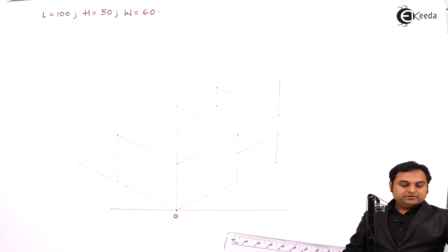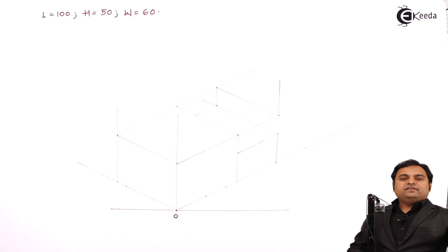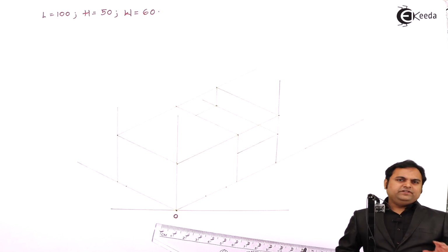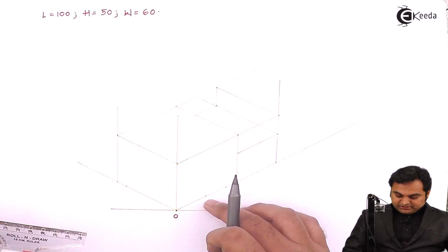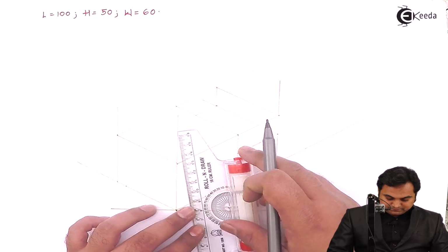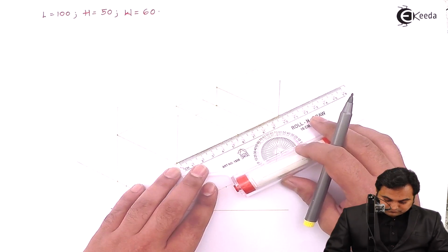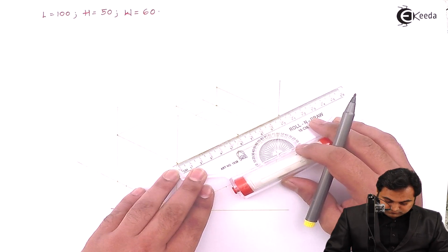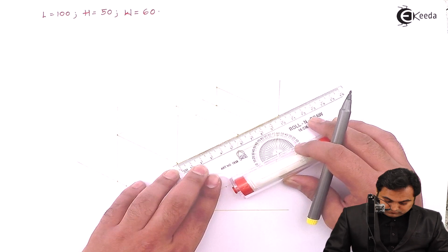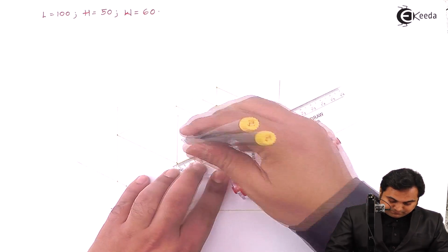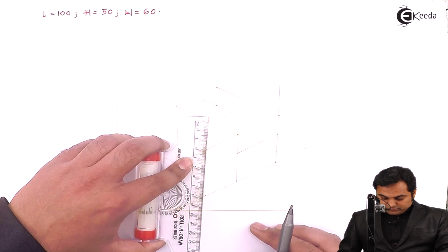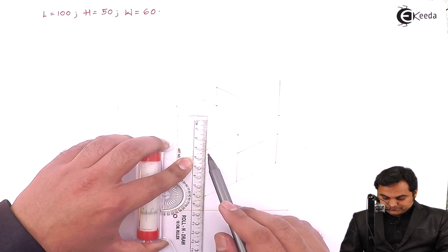This is the center, and then the semicircle is having a radius of 18, so diameter is 36. Selecting this center point. Next, from the top also I am marking this midpoint and drawing a light vertical line through these points.